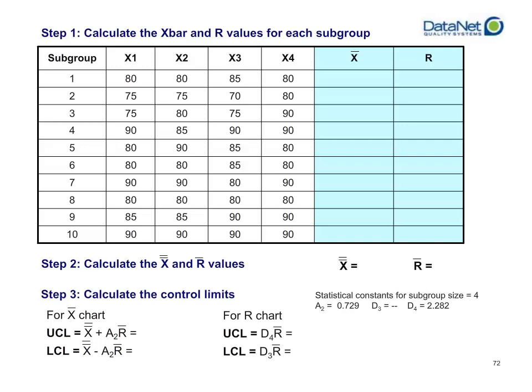Then you're going to want to go ahead and calculate your control limits, your upper and lower control limit for your Xbar chart, which is your primary chart. You're then going to calculate your control limits for your R chart, which is your secondary or lower chart.